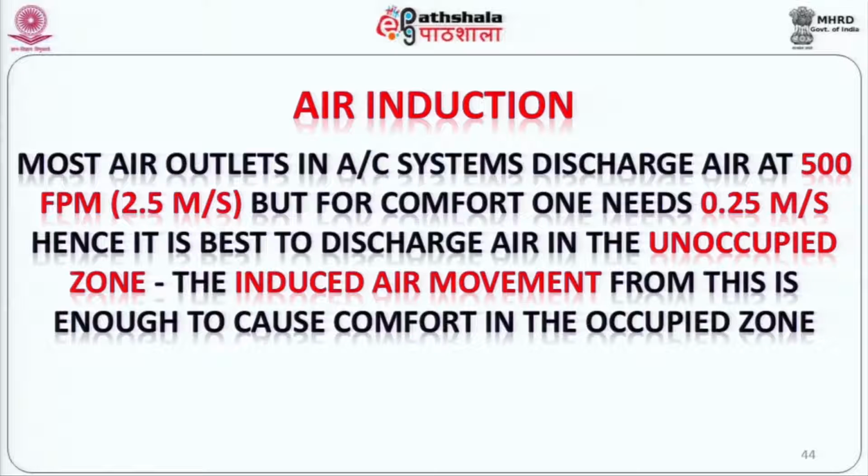The moment you have air moving at 2.5 meters per second, 500 feet per minute, at a higher area above the occupied zone, obviously there is a sympathetic air movement in the occupied zone, which generally one might say is about 1/10. So if you move air overhead at about 2.5 meters per second, in the occupied zone you get movement at 0.25 meters per second, which means 25 feet per minute. So it is just the right motion to give you a feeling of comfort.